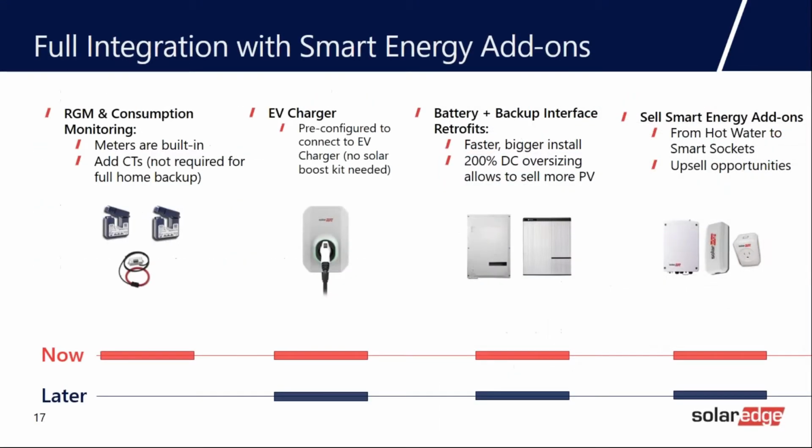All of our connected devices for Energy Hub range from CTs for import and export to EV charger capability. Previously, for our EV charging inverter, you connected a cable directly to the bottom of the inverter. That's a little bit different now. Now we have a standalone EV charger box and kit that is hardwired, 2 or 3 wires, line 1, line 2, and ground, to the inverter.